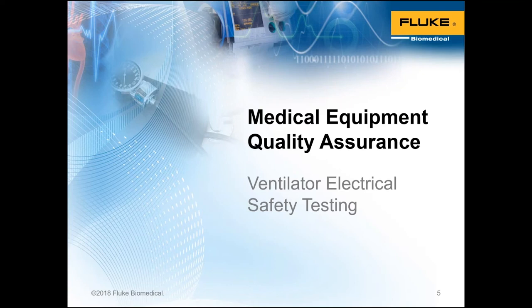For everybody else, the IEC 62353 has been adopted internationally so that we can do a better and quicker job of getting the electrical safety testing done, and so that we do not shorten the useful life of the medical device, because there are tests in the IEC 60601-1 that may shorten the useful life of the medical device. So IEC 62353 is what we're going to follow.